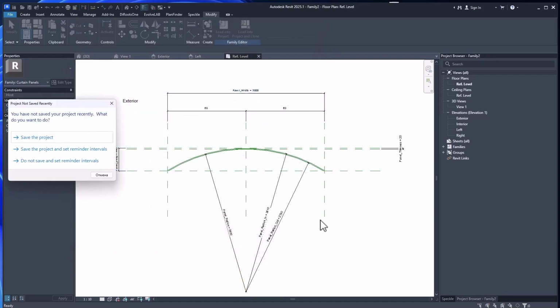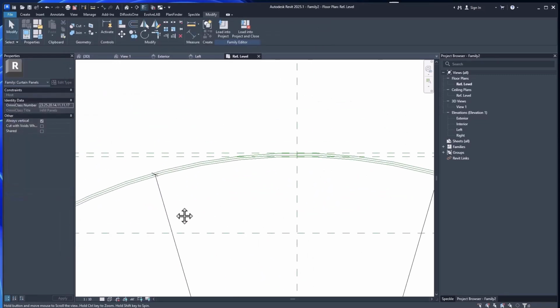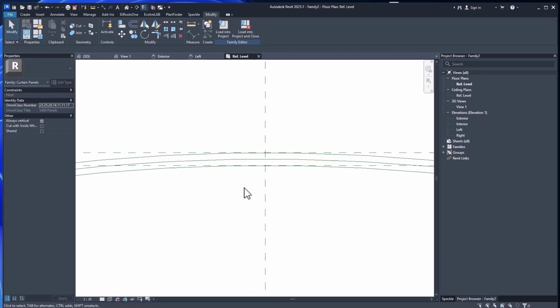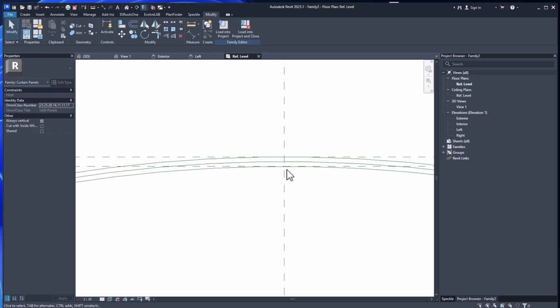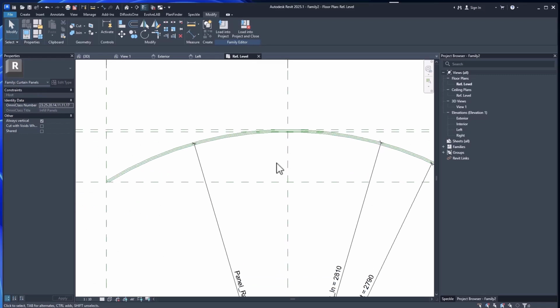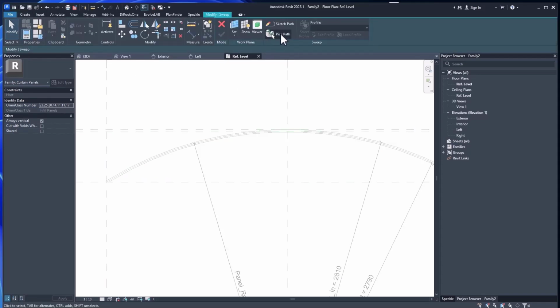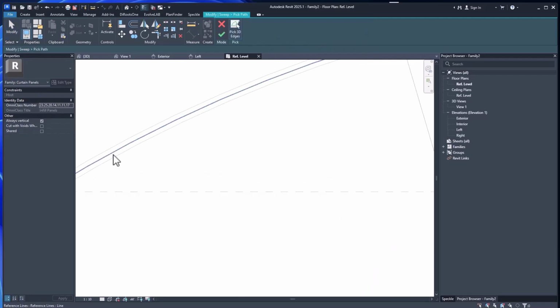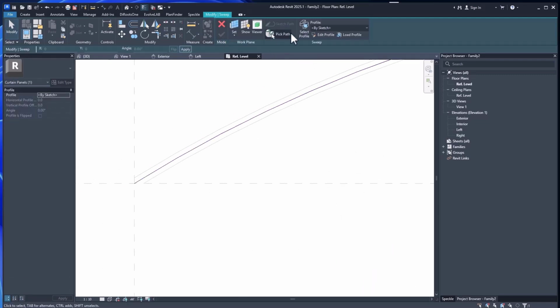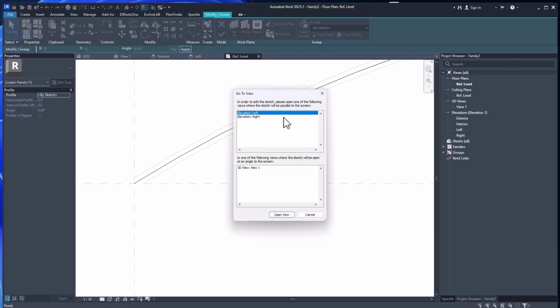Let's say okay. So we already created our panel, as you can see. Now exactly as you can see, the distance is manipulating. Now we can create geometry. I will apply, and we will improve it later on. Let's go to create, sweep, pick the path, the middle one. Let's say okay. After that we need to edit the profile, just left or right, it's up to you.